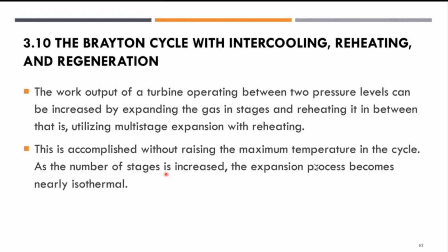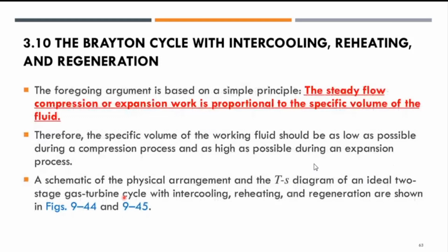As the number of stages increases, the expansion becomes nearly isothermal. The foregoing argument is based on a simple principle. What is the principle? The steady-flow compression or expansion work is proportional to the specific volume of the working fluid, in this case air only. Therefore, the specific volume of the working fluid should be as low as possible during the compression process and as high as possible during the expansion process.